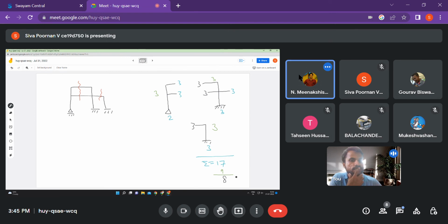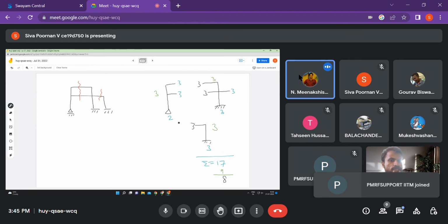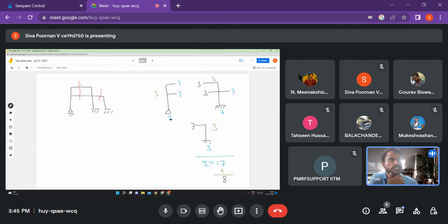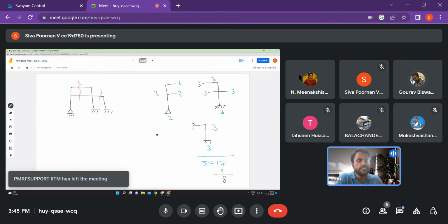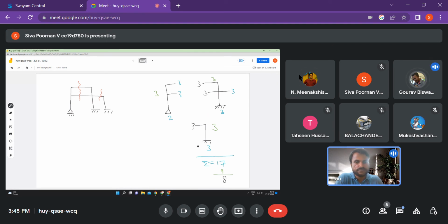Why do we need 3? External unknowns are what is counted in these 2, 3, right? Those are unknowns, though they don't come into equilibrium equations. Equilibrium equations means in a structure we'll sum everything and take summation of Fx equal to 0, right? And these two will be counted in unknowns, these 3 and these 3. Is that clear? So when you sum everything and subtract, you see that there are totally 8 additional unknowns. That means that it is statically indeterminate to the degree of 8.